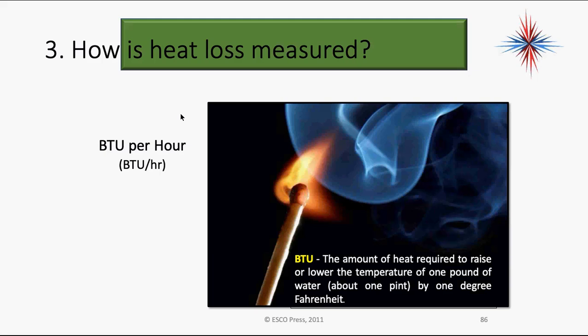Okay, so moving on, we have to talk about how heat loss is measured. BTUs per hour. Very important. This is exactly what we're doing all of our load sizing for. We're talking about BTUs per hour. How fast are we losing heat?